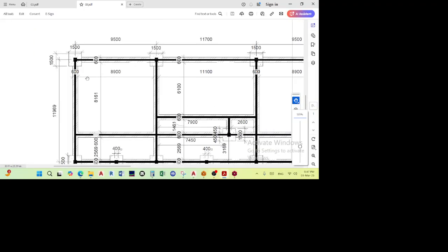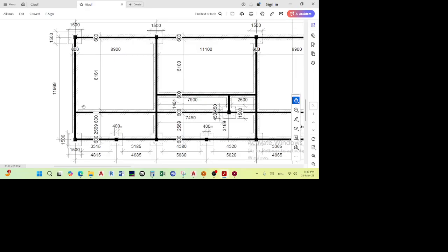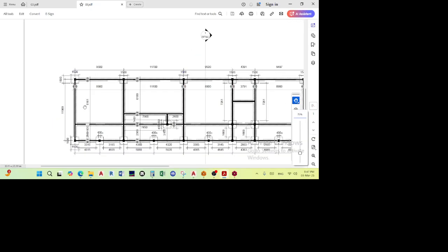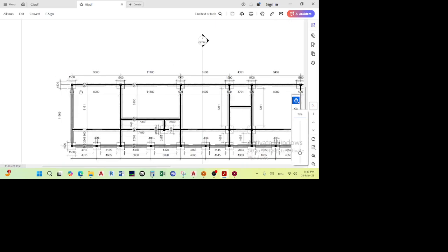Ideally, if you're a structural engineer as opposed to an architect, you need grid lines so that you can reference your structure elements like bases, columns, beams. For example, if we didn't have any grid lines, it would be difficult to identify this column. What would you call it? Unless maybe you've numbered them as C1, C2, C3, or any type of identification, it becomes easy.